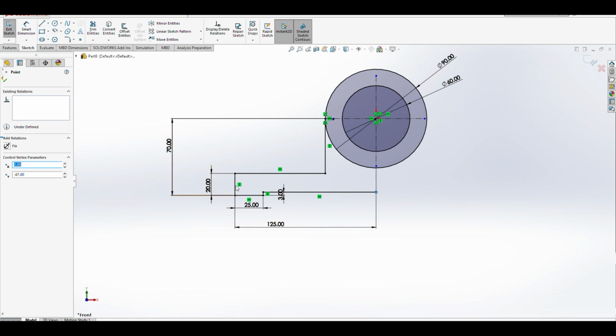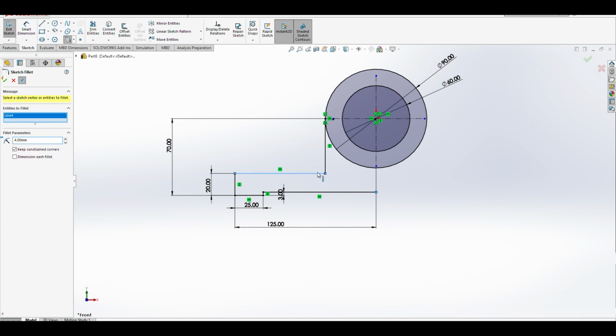There's also some fillets. Okay, those are little rounds. They rounded off the corners a little bit, and it says R4 typical, or TYP. The TYP means typical. So I'm going to click up here under fillet, and I'm going to change my parameters to 4, okay. And what I'm going to do is just kind of select these two, and I believe the other fillet is right there. Green check mark, and we got our R4s in. Okay, so we got our little rounds that are in there.